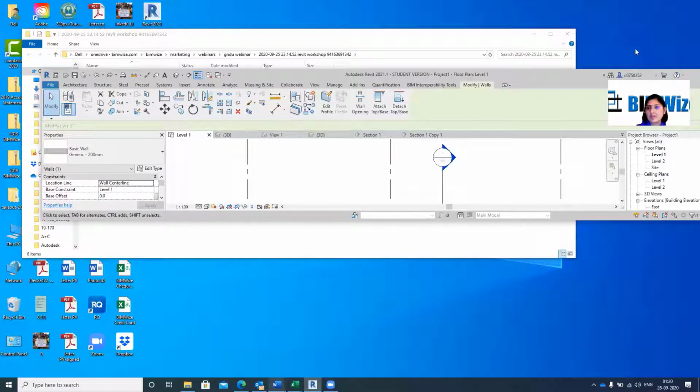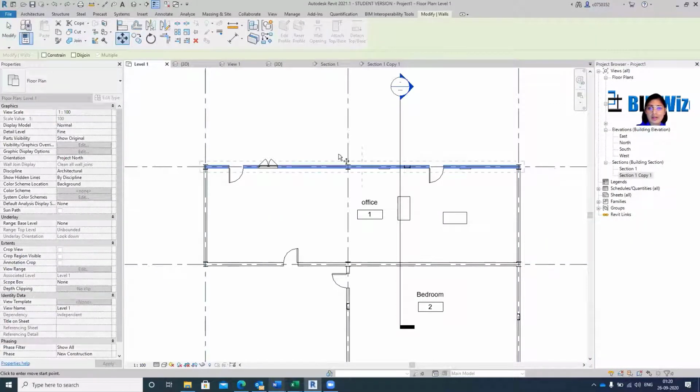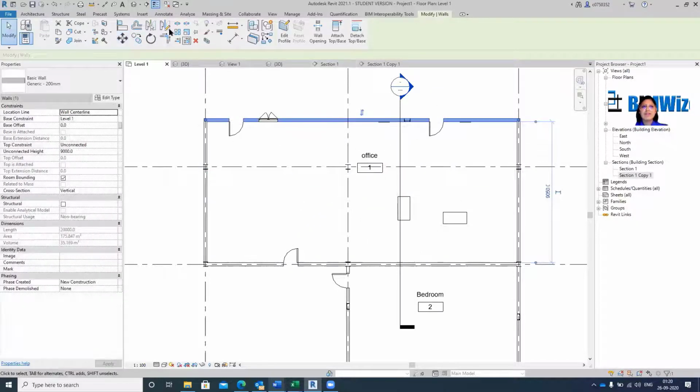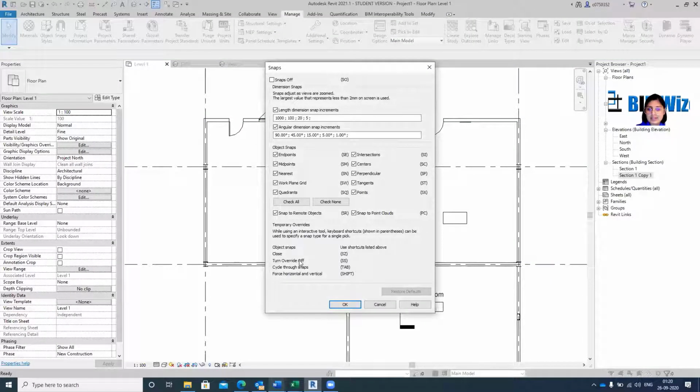Okay, perfect. Now let's say I want to move this wall, and now I want to pick up like exact middle. Instead of just going here, doing anything, I can just go SM and it will pick the middle. And so there are a few commands in there. You can go to snaps and you can see these commands. So there are SZ is for closing, SS is for turning and override. We can also turn on and off snaps in here. There are angular snaps, and these are shortcuts in here.